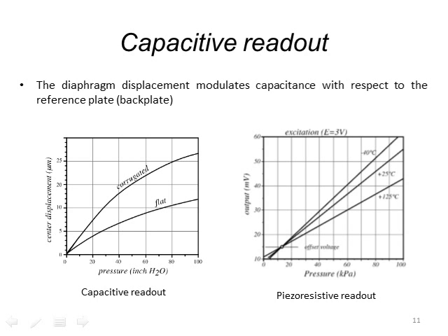Now we can also do a capacitive readout. In a capacitive readout, it's easier to implement. So these are basically plates that are moving, and I won't show examples of these because I think you know how they work by now. In this case, you would have a plate that's going to be moving, and you can still do a delta C type of measurement. The capacitive readout systems are interesting because they're a little bit easier to manufacture, and they can be integrated in an easier way with modern microcontrollers on the same chip.